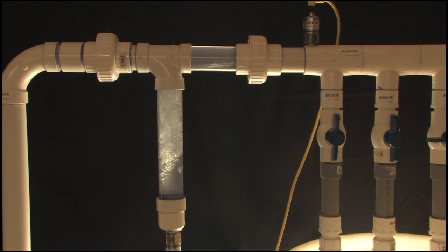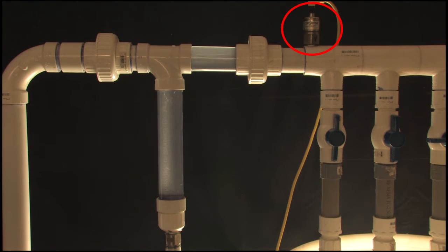You see the stub filling up, and now you can see the air bubbles dancing around, but only up here where the turbulence is. I have a small valve on the inlet pipe so I can inject air into the system to make this easier to see. I'll open that valve a little bit, and we can see how fast the air bubbles are moving through here and smashing into this sensor.